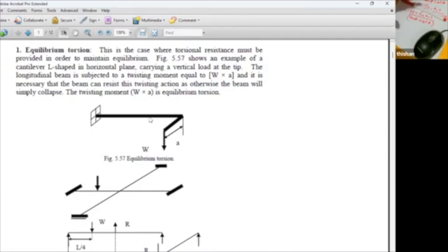Yes, it is clear. Try and avoid torsion. Try and make the loads axial with the center line, coincide with the center line. But in some situations like transfer beams, we can't do that. Then in such situations, we have to resist it. But there's another way actually to make it coincide.